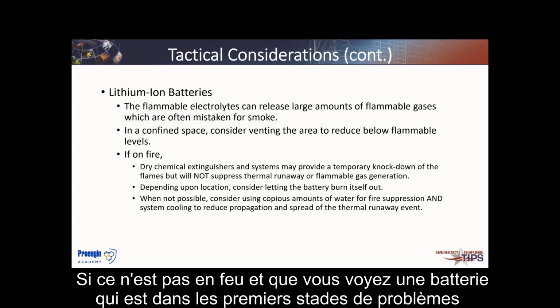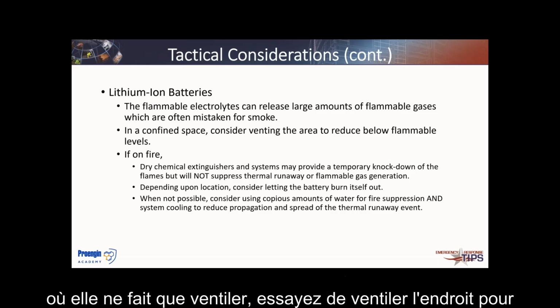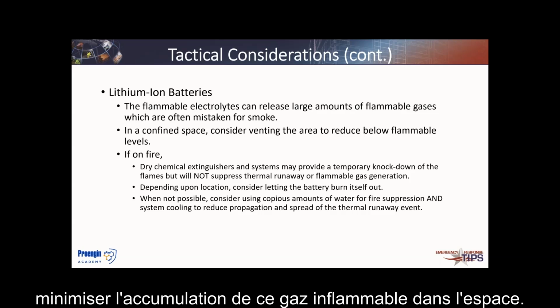That's if it's on fire. If it's not on fire and you see a battery that is in early stages of problems where it's just venting, try to vent the area to minimize the buildup of that flammable gas in the space.